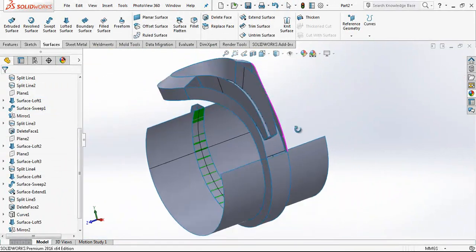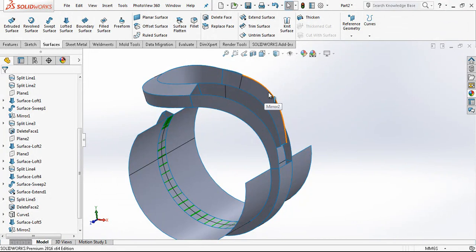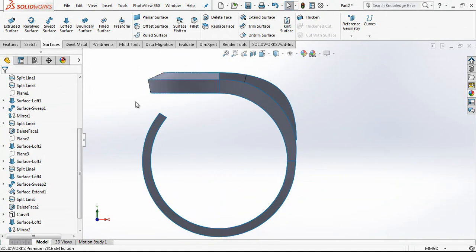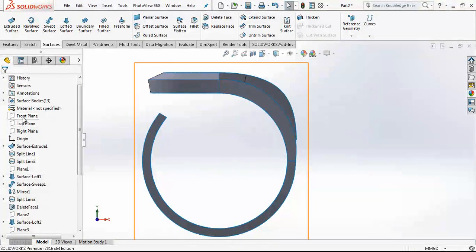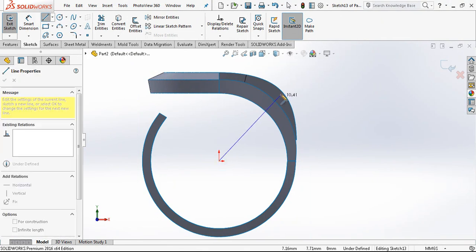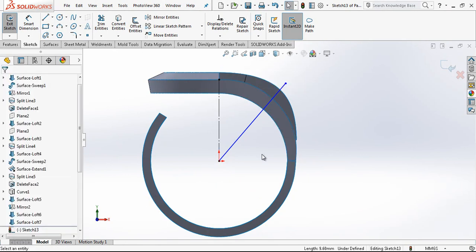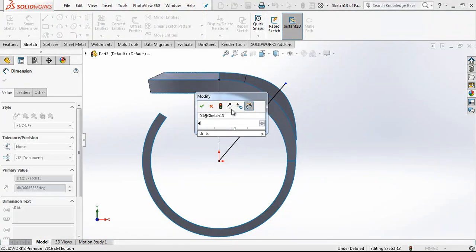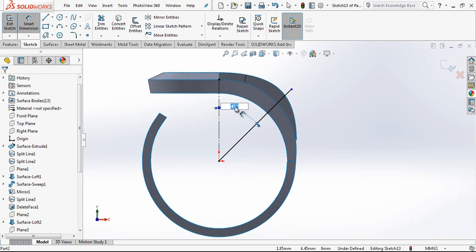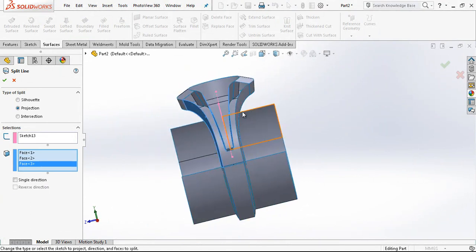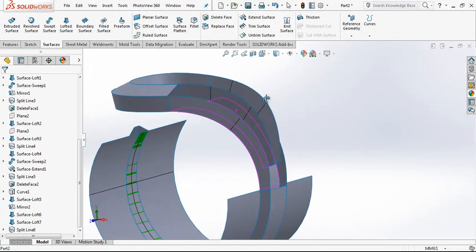And also this surface was opened with the help of loft. I also created, and now I'm just going to create one control point on the model for the filled surface operation. This is going to be around an angle of 45 degrees, or let's say 42, around the highest point of our spline.